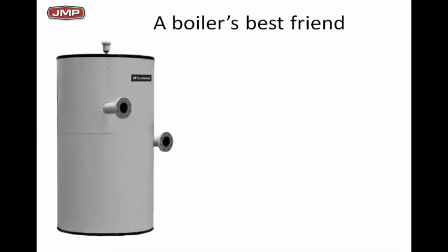We're seeing more and more buffer tanks. Now, by nature, buffer tanks hold a huge amount of water, and guess what? Very low velocity. So they really do make a great place for air separation because we've got the water down below 6 inches per second. You can put an automatic air vent, a 107A air vent, on top of these things, and they do a nice job of separating air.